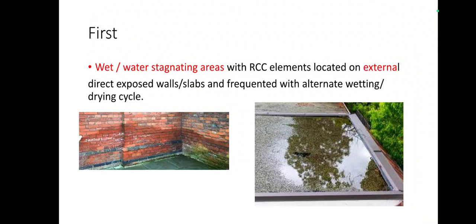As per the record and the literature survey, it is observed that if water is standing on a concrete surface for more than 5 minutes, it will try to enter the concrete, and if the cover concrete is not adequate enough, it will reach the reinforcement and thereby initiate corrosion.